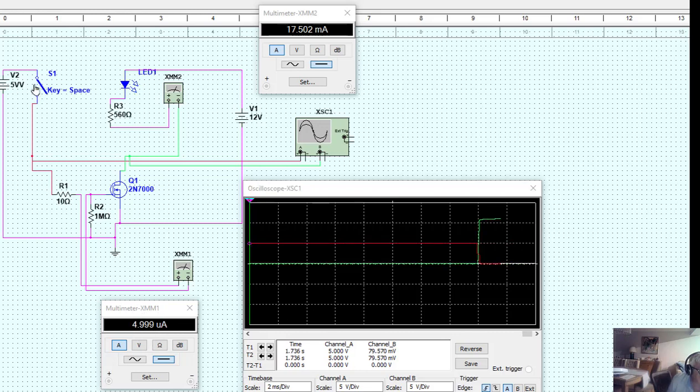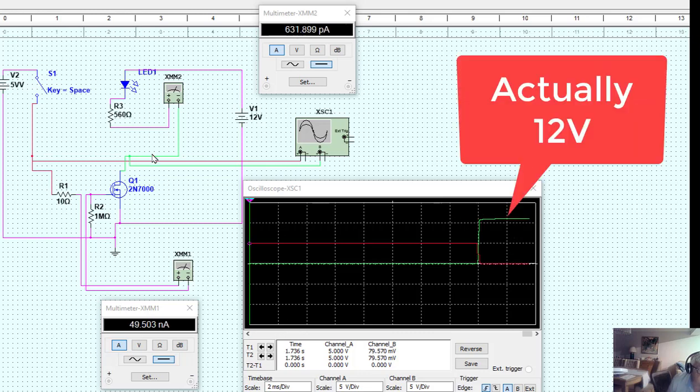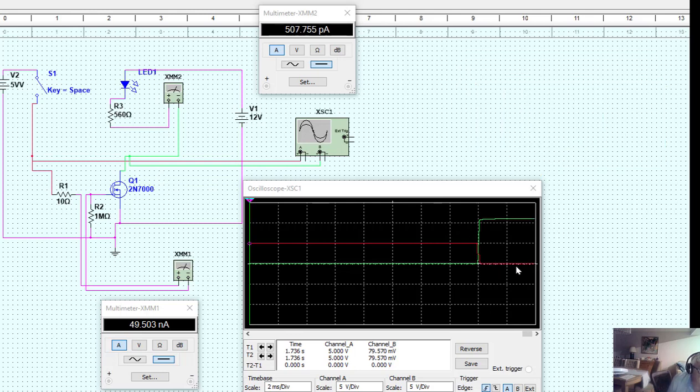And if we open that switch again, we'll see it jump there on the oscilloscope to 5 volts, because effectively it's turned off, and the gate voltage is 0. So gate voltage 0, high voltage on the drain. Feed 5 volts to the gate of the FET, and you saw it switch the drain to ground, and now we've got a high voltage on the gate of the FET. Hope that makes sense.